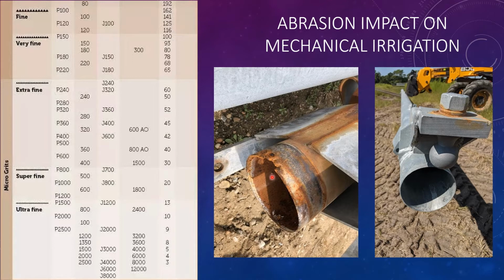But you can see here, and I don't know if this is upside down or right side up, but it doesn't matter, you can see that there's an abrasion of the entire surface, and that would be what I would expect. You can see some deposits of rust on the bottom, and you can see that as it worked through the protective coating, we started to get rusting. And this is basically a used pivot, but it's not had near as much abrasion. But even here you can see that there are issues with some sacrifice of the protective coating.